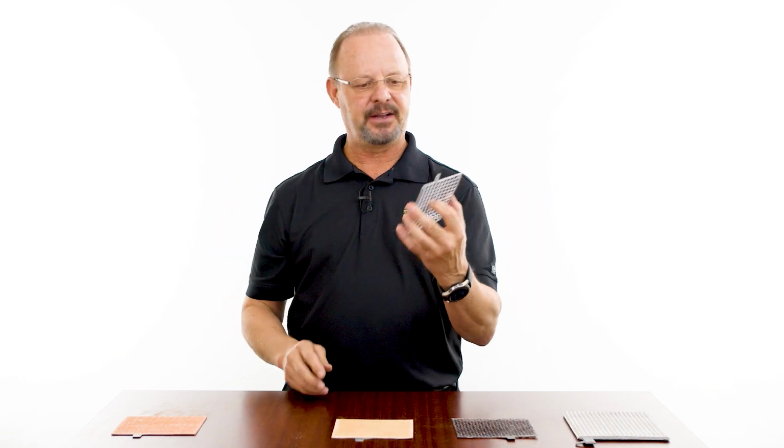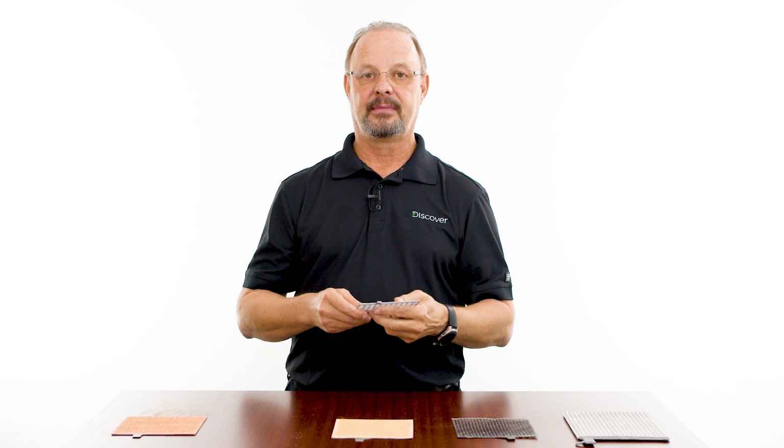So if you have 10 of these grids in one battery, and the grid surface area gives you 50 cold cranking amps per grid, 10 of them will give you 500 cranking amps. If you want more cranking amps in your battery, you want more grids. Alternatively, if you're less about cranking amps and more about capacity or reserve capacity, amp hour and reserve capacity do not come from the grid. Amp hour and reserve capacity come from the active material that we're going to talk about next.